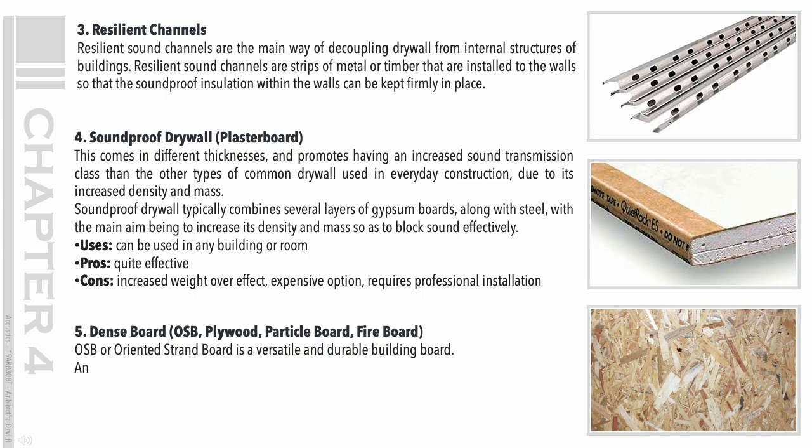3. Resilient channels. They are the main way of decoupling drywall from internal structures of buildings. They are strips of metal or timber that are installed to the walls so that the soundproof insulation within the walls can be kept firmly in place.